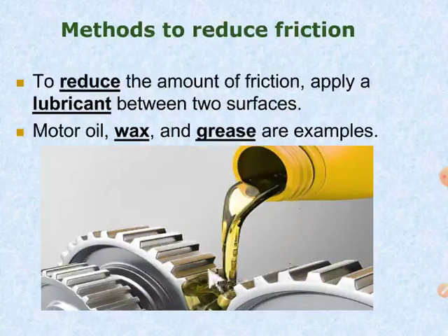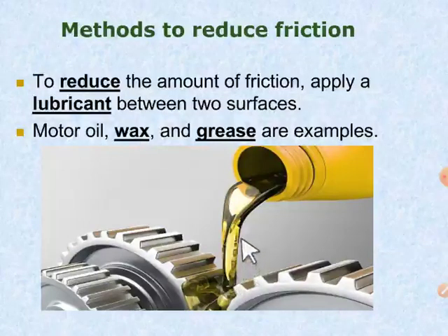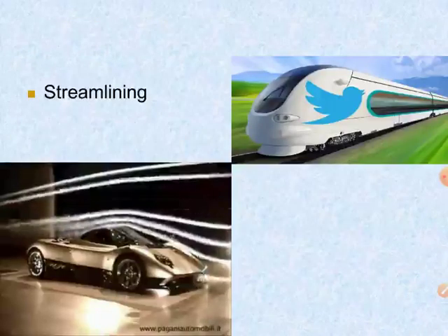Your graphite powder is one of the best materials to use to reduce the friction. But in this case of the gear system, in order to avoid heating due to the frictional force, it is used with motor oil. If you are using graphite here, that means a solid lubricant, then it will not work. Why? Because more heat may be developed. If you put your motor oil, then heat may be greatly reduced.